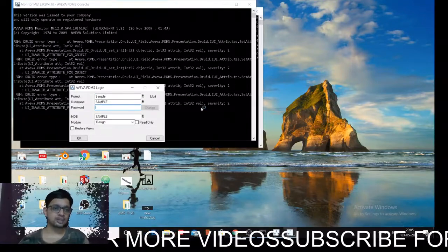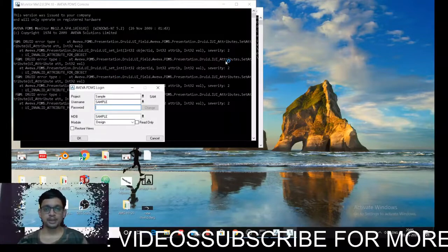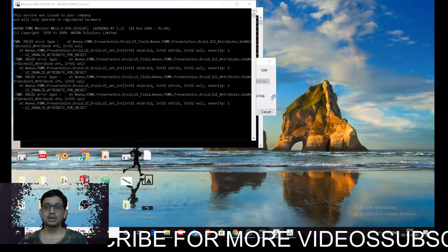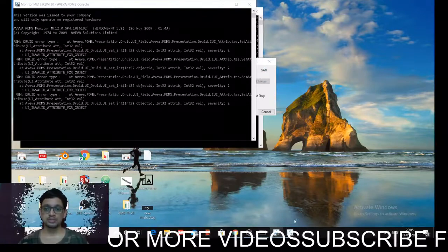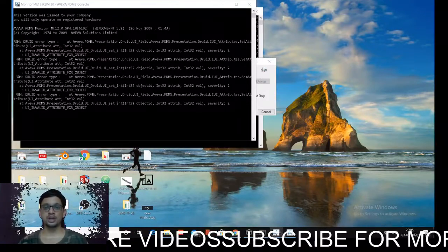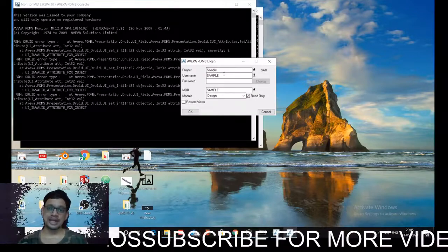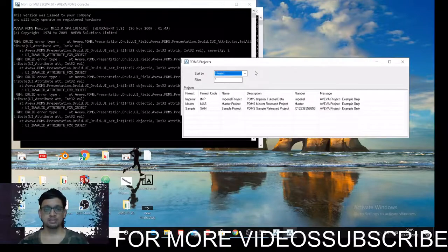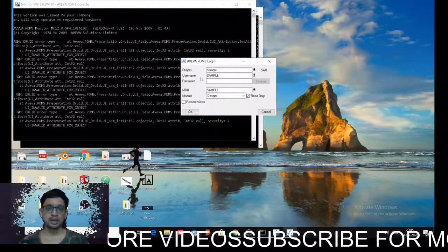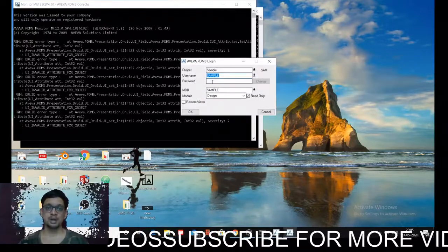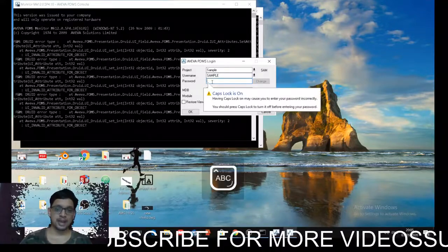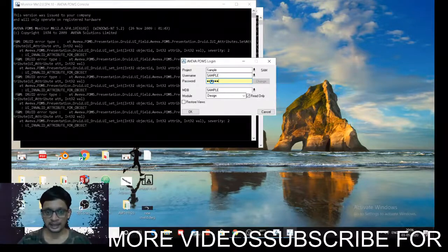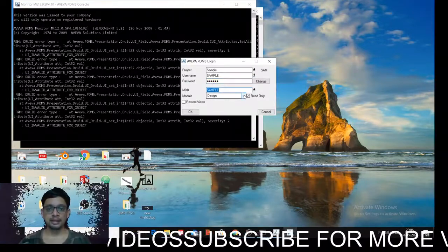Now this is the PDMS login window which you get. If you have a server, you can always go with the actual username and password. We are using a standalone system here, so we will be logging in using sample. Everything will be sample. You can select a project name if you want. We will be starting with the sample. We will use username as sample and password as capital SAMPLE. Enter there and then we will go for the module.